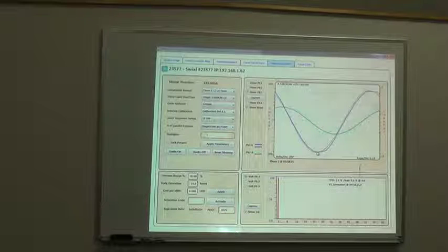Well, if it's 50%, when you say phase shift between the voltage and the current, which one of the currents? You have more than one current. You have current all over, right? So which one of them? To truly find out what the true power factor is, you need to find the average wave that represents all of those waves and measure the power factor between those two phases.